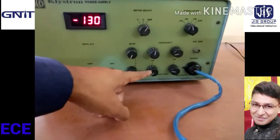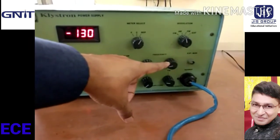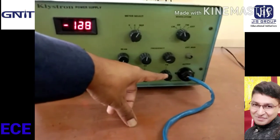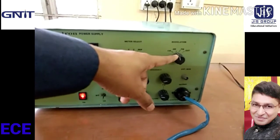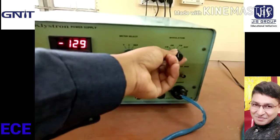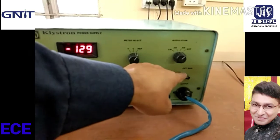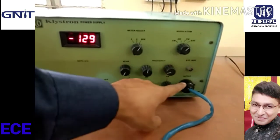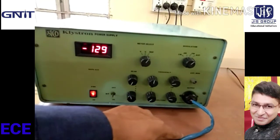This varies the amplitude for amplitude modulation, this varies the frequency for frequency modulation, and this varies the amplitude for frequency modulation. This is the modulation selector switch. The modulation modes are CW, AM, FM and EXT. In EXT mode, select the EXT signal and feed it at this point, and this is the output of this power supply.